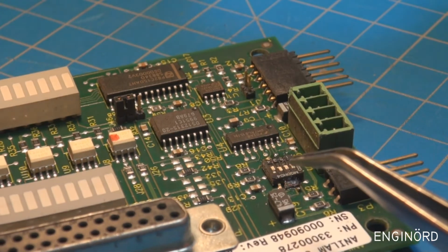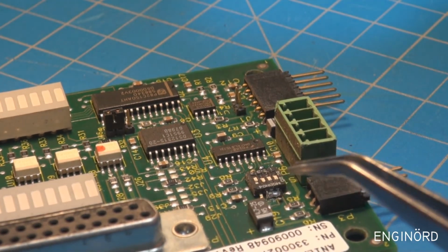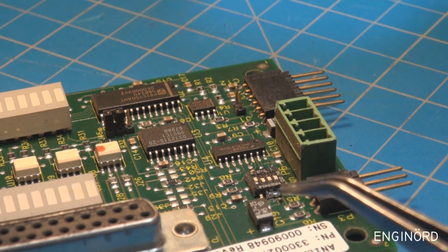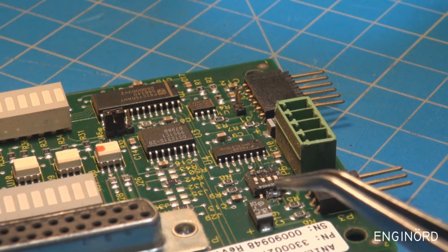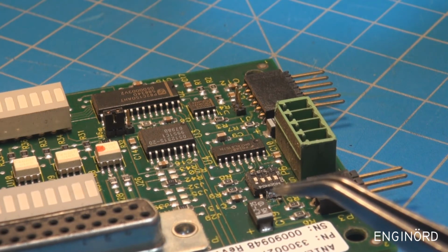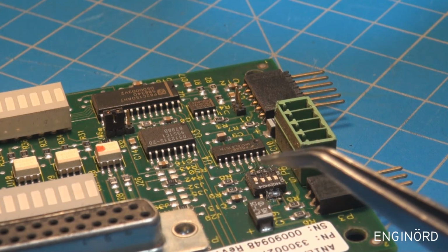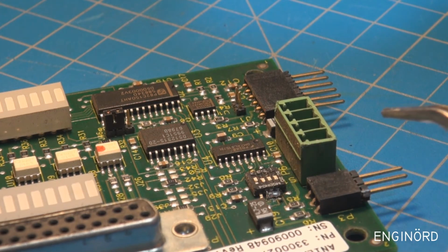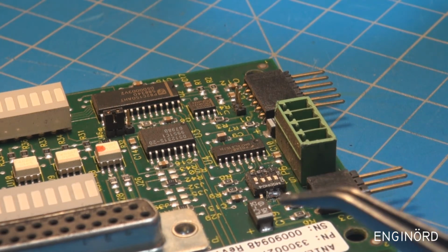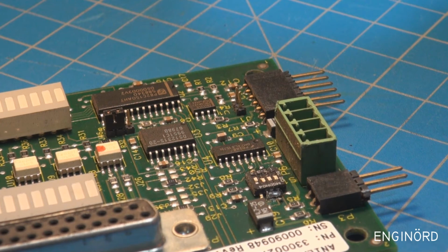What this dip switch essentially does is pull high or pull low. This probably pulls high. There are some connections to one of these ICs, and it is gonna pull those legs high, to the 5 volt or 3 volt, whatever the voltage for this board is. The next thing, I'm gonna put it back together and we'll see how it goes.